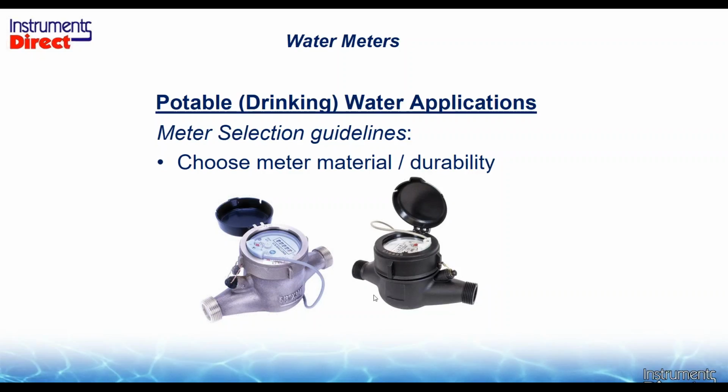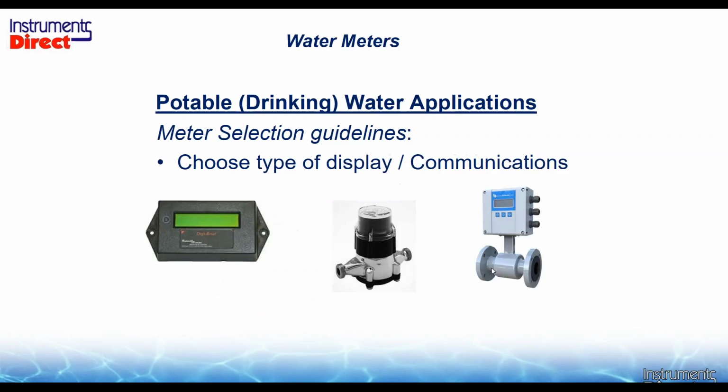So this meter here is $150 and this meter here is $300. Not a whole lot of difference unless you're buying a couple hundred of them. Then it makes a significant difference. Well, you need to look at the environment. The temperature specifications are everything the same. You need to look at the traffic and the place where this is actually installed. Some places, this comes down to local ordinances and certain restrictions on where you can and cannot use this, but they're making this device the same way, just a little less expensive. And if this material is compatible, you can buy a less expensive water meter.